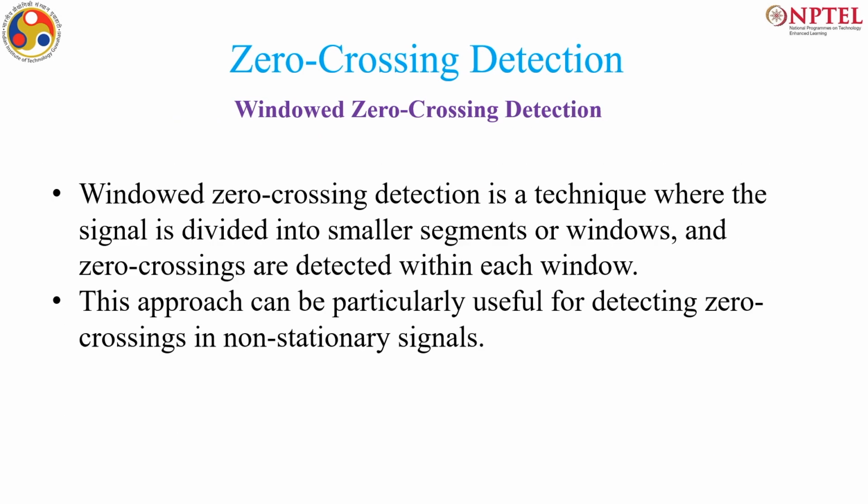Of course, mirroring is also not a perfectly accurate technique, but it will ensure that your boundary values are handled. Now, some signals may have some switching nature. Switching nature means the signal values have a trend like this. This is often called a non-stationary signal, where the signal mean is deviating from the baseline. This is also very common in biomedical signals, and it is called baseline wander.